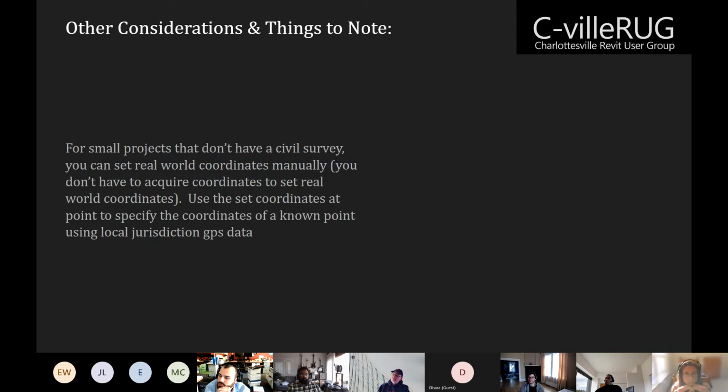No, I think you could, and you do have a choice at that point. You could set it yourself, and then you would know that it was different in your file than it was in their file. What that would mean is you would not be able to use shared coordinates to link your file or link their file into your file, and you would need to tell them that they can't use shared coordinates when they link your file into their model.